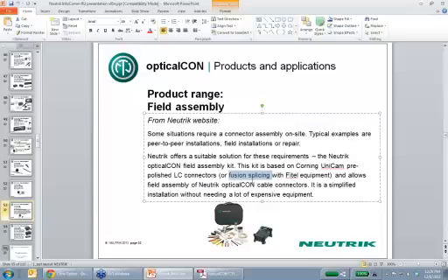A lot of users say, well, what do I do if my opticalCON cables fail in the field? Well, since we have that LC compatibility, right? You can plug LC connectors into the front of an opticalCON duo chassis connector. We say, get an inexpensive little kit like the Corning Unicam kit or the Belden Brilliance kit, and bring some LCs with you. And then if you have to, snip that cable end off, terminate it with some LCs, plug those into an opticalCON duo chassis connector, and you're good to go. It's going to be faster and it's going to be less expensive than trying to do it on your own. And then, when you have some time, send your cable back to BTX for repair.